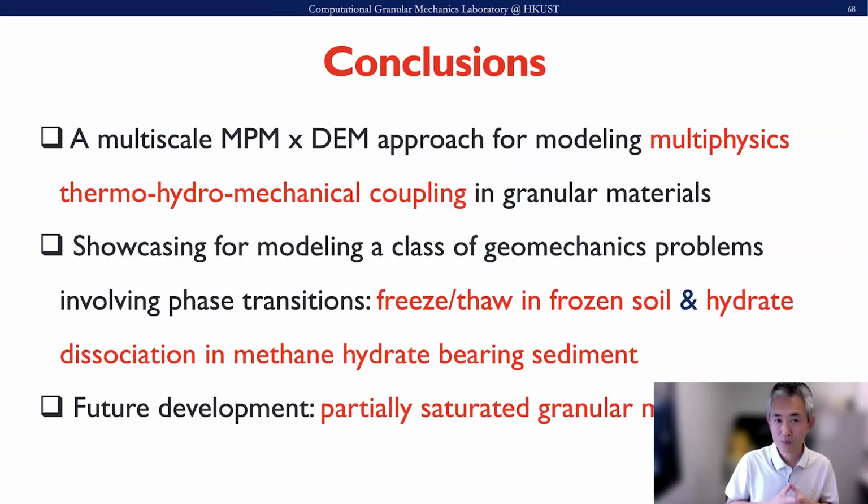So here are some quick conclusions before I finish. This MPM+DEM coupling is basically an extension of the FEM-DEM multiscale coupling to large deformation problems. And further, we can incorporate multi-physics problems, thermal hydromechanical coupling processes, to tackle more challenging problems.